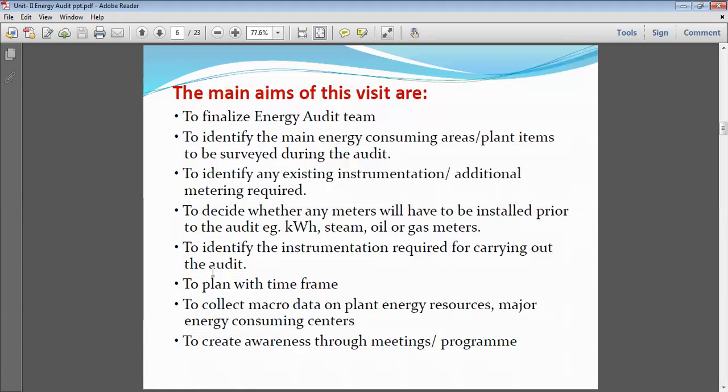But compressed air we cannot identify, because there is no smell and no visual signs. So such types of leakage detectors are to be used to identify the leakages in the pipelines. It is found that leakage is simply a wastage. So only by trapping or reducing the leakages in the pipeline and in the other systems, definitely we can carry out the energy conservation program.